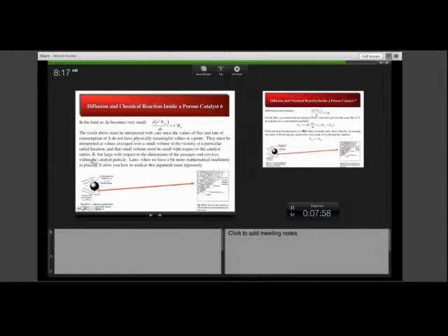And so even though the reaction is only occurring at the surface of the catalyst particle, we still have the appearance of a reaction term in this mass balance, and that comes about solely because we have averaged over regions that include both the gas phase as well as the particle surface. And so that points out one of the caveats of this approach. We have to be careful in the way that we interpret the values of the flux and rate of consumption of A, and so they have to be interpreted as values averaged over a small volume in the vicinity of